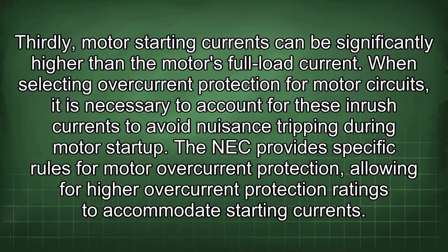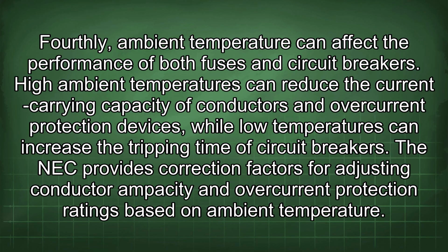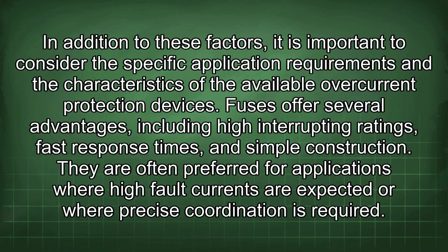starting currents. Fourthly, ambient temperature can affect the performance of both fuses and circuit breakers. High ambient temperatures can reduce the current carrying capacity of conductors and overcurrent protection devices, while low temperatures can increase the tripping time of circuit breakers. The NEC provides correction factors for adjusting conductor ampacity and overcurrent protection ratings based on ambient temperature. In addition to these factors, it is important to consider the specific application requirements and the characteristics of the available